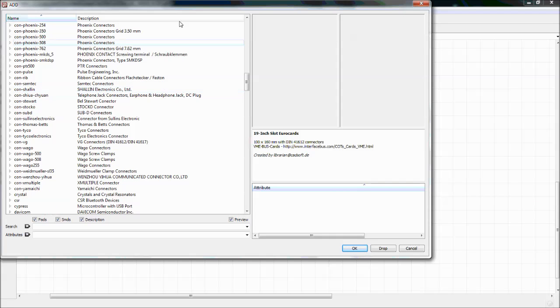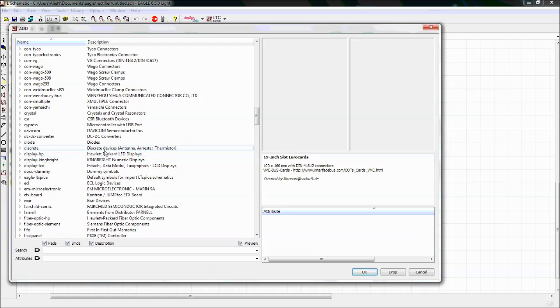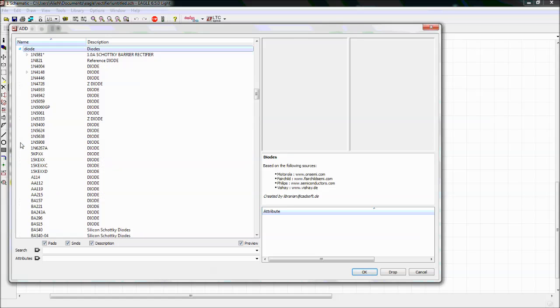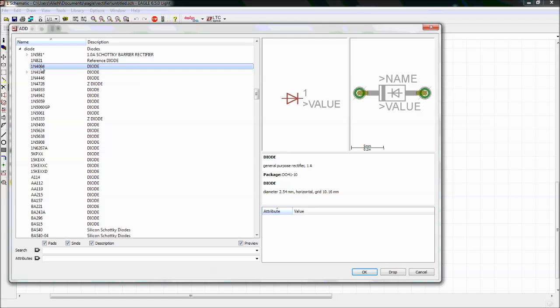Okay, now we are going to design a rectifier, of course. So we will need a diode. As I said, full wave and a bridge connection. We are using bridge connection, so we will use 4 diodes. Now you know 1N4007, these are general purpose diodes. You can see it also. It is a general purpose rectifier diode whose maximum current is 1 ampere. Okay, diameter is 2.54 mm.